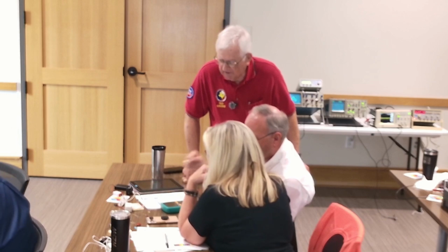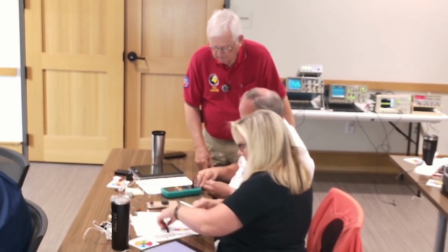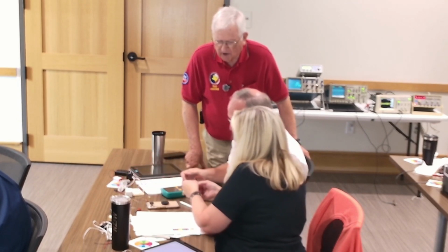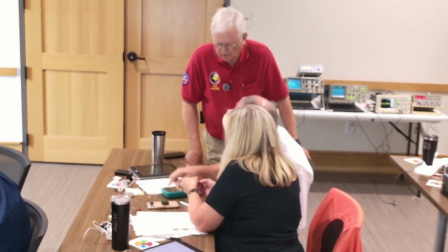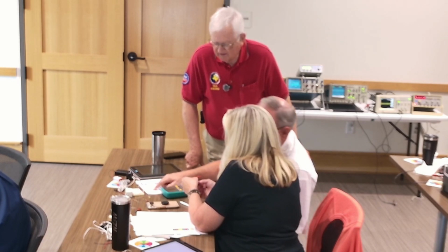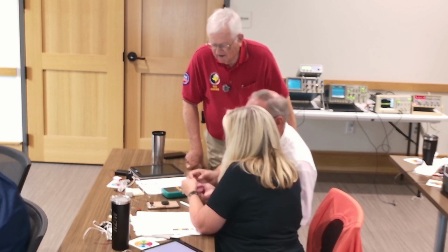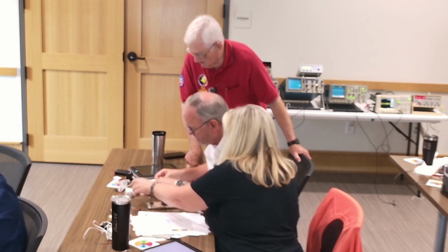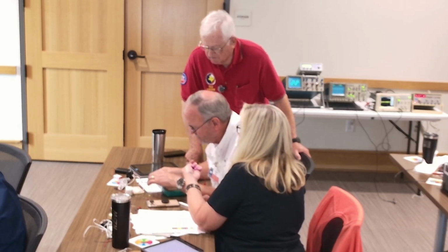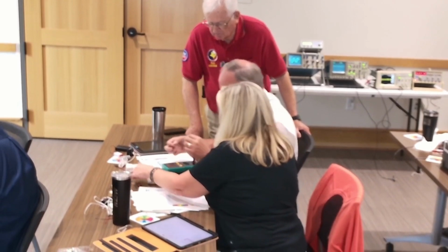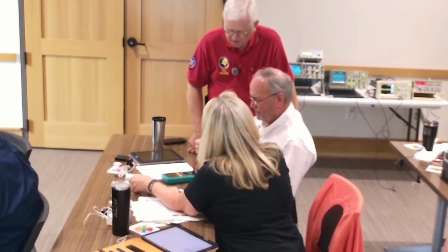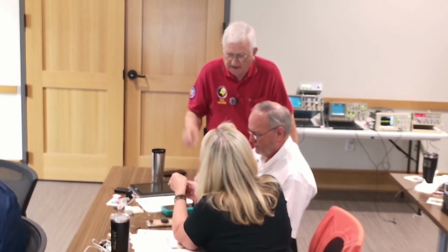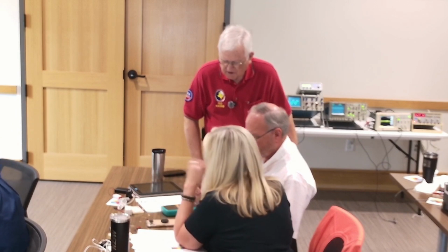So try one of these little guys. We have to look at them to figure out the values. Some of them are just marked, and some are not marked very well at all. Some have colors, some don't. That's 100 volts. Some can be a little hard to see. I'd say just hook it up and see where it goes. These aren't polarity conscious, they don't care. How do you decide if it's polarity conscious? If it has the minus marked on one side. If it doesn't have a minus marked, you don't have to worry about it.